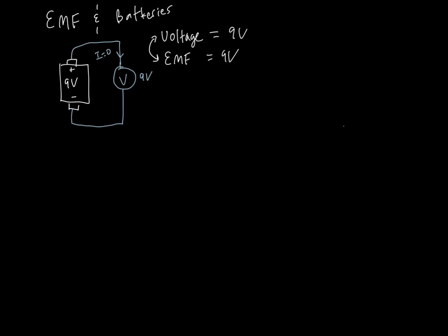A voltmeter measures the potential difference. Potential difference, so another term, across the terminals of the generator. So the potential difference would even be 9 volts. Again, assuming that the current is equal to 0, so this voltmeter is ideal. Now I'm going to prove this, but we need first a good definition of the potential difference.